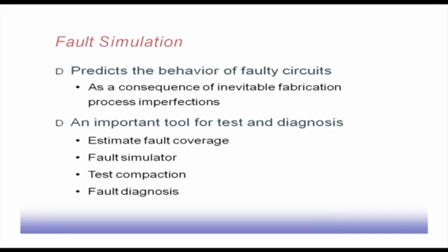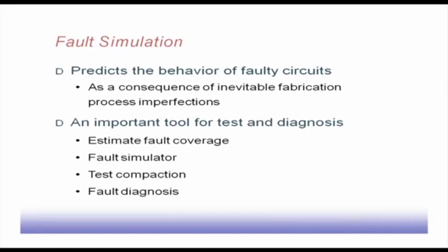That is the problem of diagnosis. Fault simulation can tell us that if you get this type of behavior, then possibly the fault is somewhere here. If you get some other response for this pattern, then possibly the fault is somewhere else. That helps us in pinpointing the fault locations.